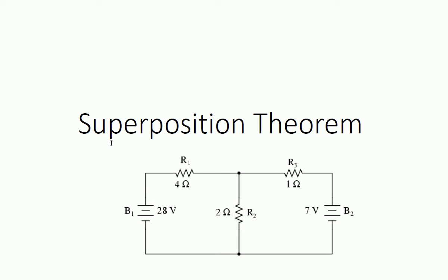So we're not going to bother for the assignment with current supplies, but we're just going to use the voltage supplies. But if you've got a voltage supply, and you've only got one circuit, just a voltage or a bunch of resistors, we are back to bog standard Ohm's law. And you do this twice. You do this once for this side and once for that side. And again, follow the mouse, once for that side and once for that side. And then you've got a different set of values, and you're just going to look at all the voltage drops and how the current flows, and that's it. You just subtract them or add them together, depending on how the voltages and currents flow, and we've done it.